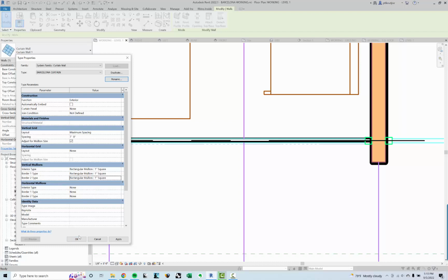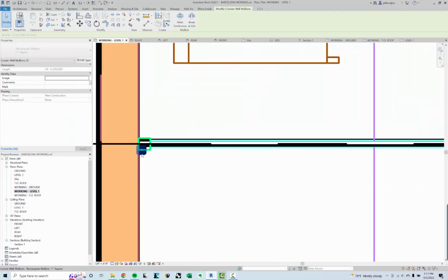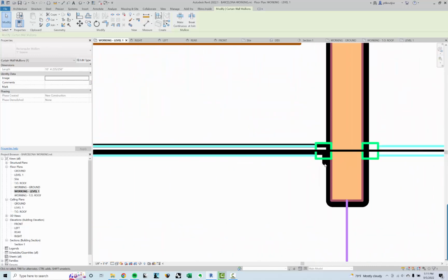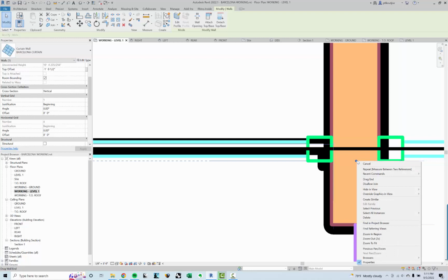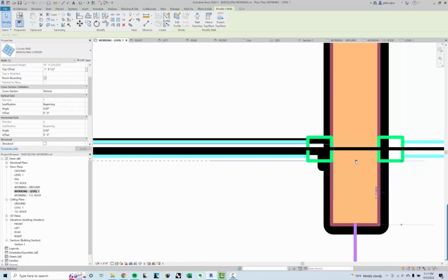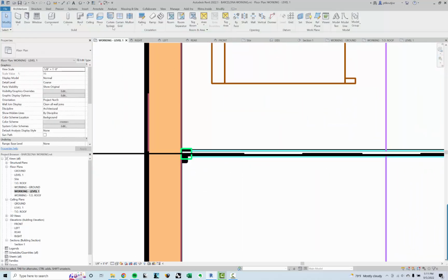So I've got my vertical mullions. I don't think there's any horizontal, so we're just going to keep it like that. And I'm actually going to get one that's pretty close to where it's supposed to be in the middle. I think what's happening is because of where it stops here and there. Well, yeah, see, so this should actually come into here. I think I need to, this is a little trick, right click here and go to disallow join. Why is this not working? This is, again, standard Revit, frustrating stuff of how it's not behaving how you want it to.